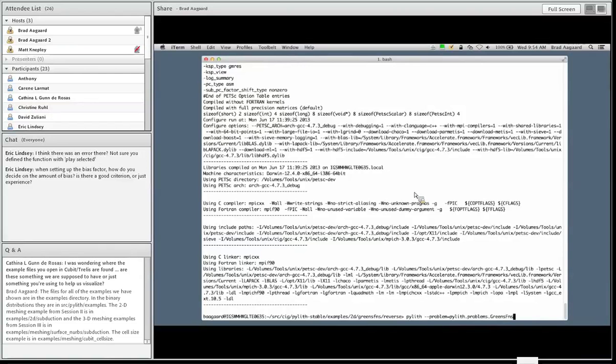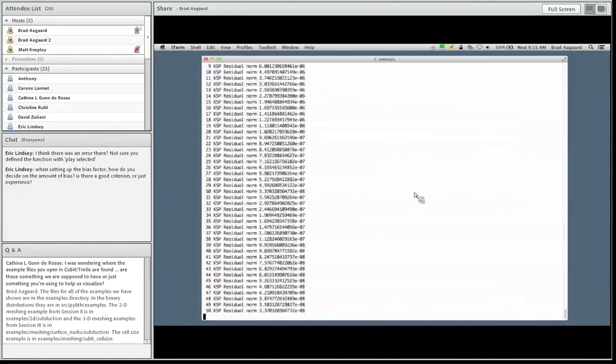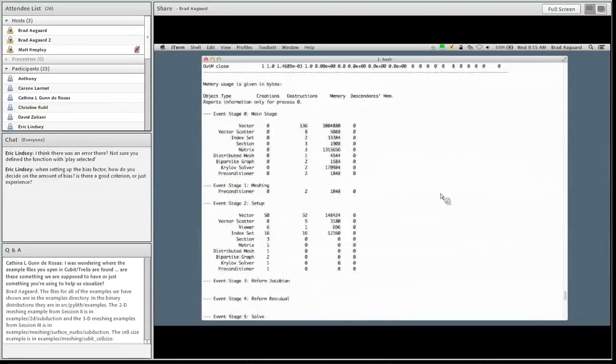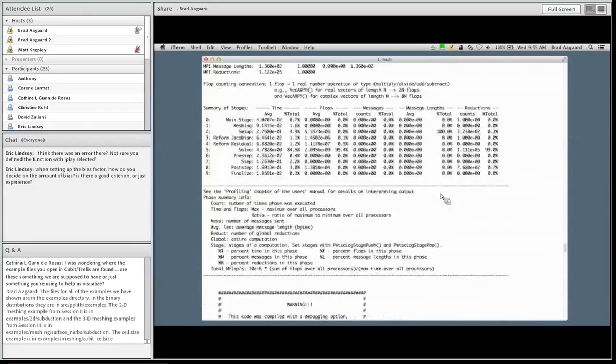So here it's running. You can see it's doing a bunch of linear solves. Look really quickly: instead of saying advancing from time step to time step, it says I'm computing response to impulse 26 of 26. It tells you how many impulses it's going to compute, so you have an idea of how soon it will finish. When it does each impulse, it'll say I'm doing impulse 1 of 26, 2 of 26, and so forth. Each one of those impulses has its own linear solve.